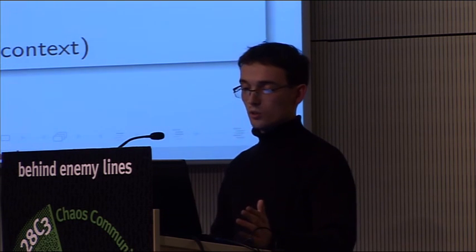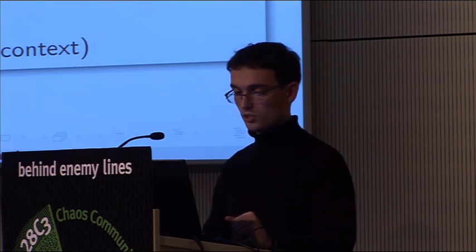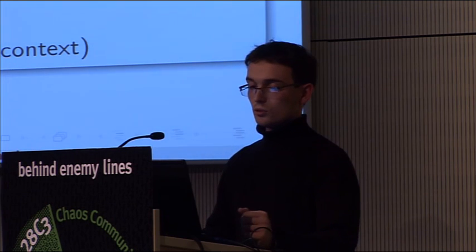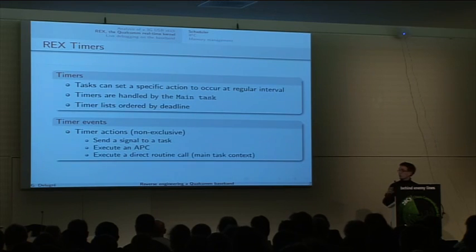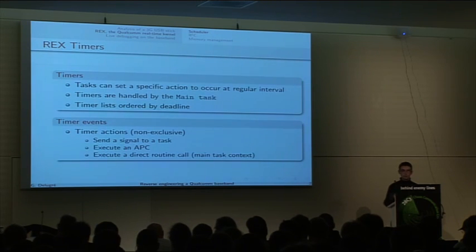The operating system also handles timers, of course, because it's a real-time operating system. You can set a specific action to occur at regular intervals. It's very used in the kernel because, in the RF world, you have to do some processing at various intervals. Timers are handled by the main task: when it has processed the creation of all the tasks, it enters a loop, checking for timers to fire.